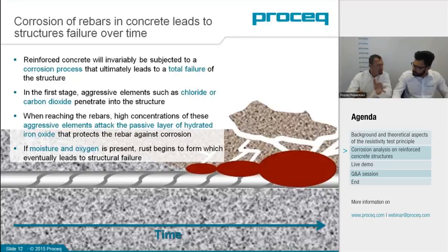Keep in mind that at this point we still have seen no damage in the concrete. It just no longer grants protection to the steel. Now, especially if other aggressive agents are present, such as chlorides, corrosion will begin. And the fact that corrosion begins will involve actual damage to the concrete.